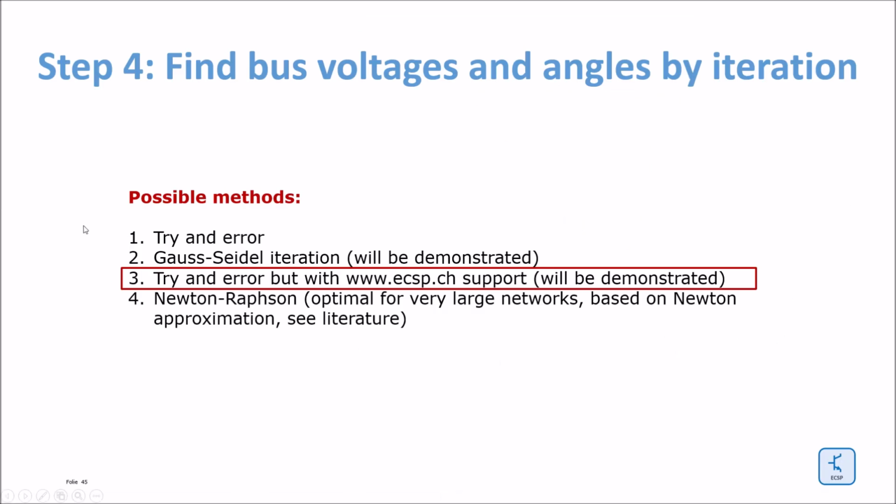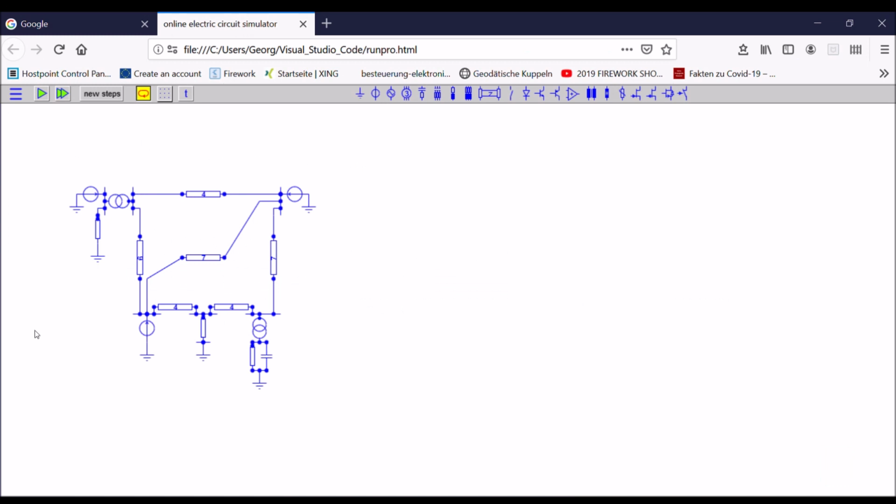At the end of this lecture, I would like to make a demonstration where you can see in a more hands-on manner how you can achieve a very similar result as we have shown before. So this is now my program I'm proposing to you to learn. You see the network. The only thing which has changed compared to what I've shown before is that I have introduced here and here a transformer so that I can measure the sum of the power coming from the generator and the load. So here I get the sum, the same thing is here.